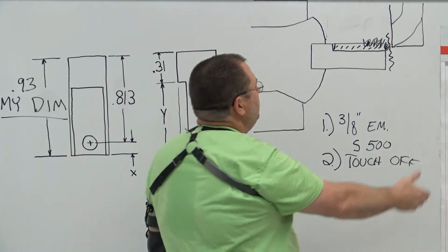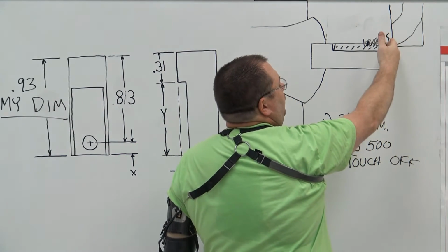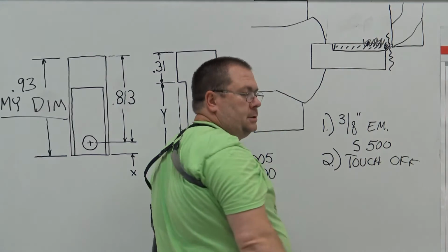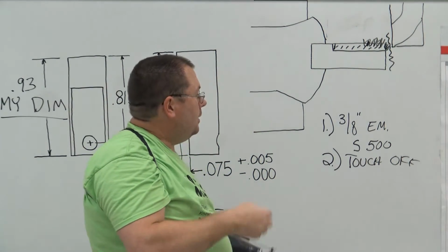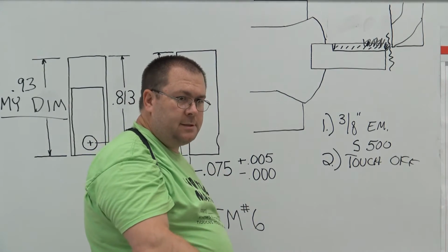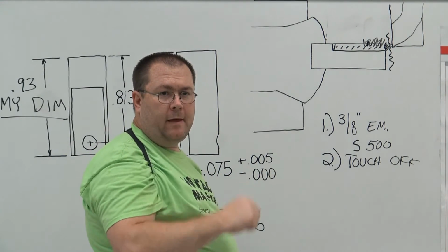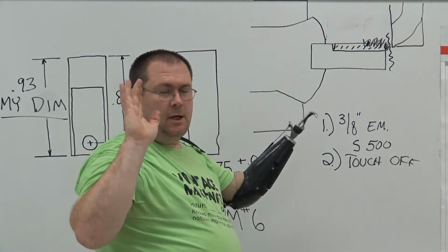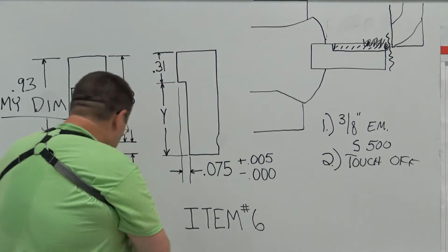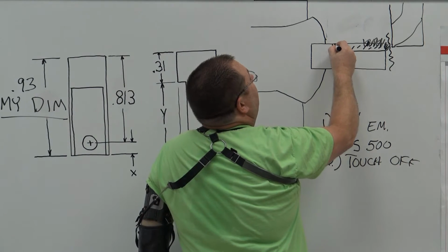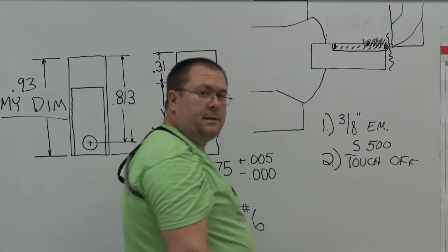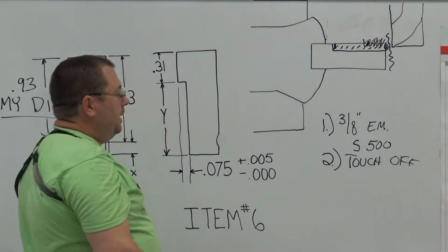Start my spindle. When the end of the tool starts to touch, my dial should be set to 0, right? As soon as I hit 0, I'm going to go 600 thousandths. 600 even. Okay? What that does is gets me within 20 thousandths of that end. So we're going to feed in.